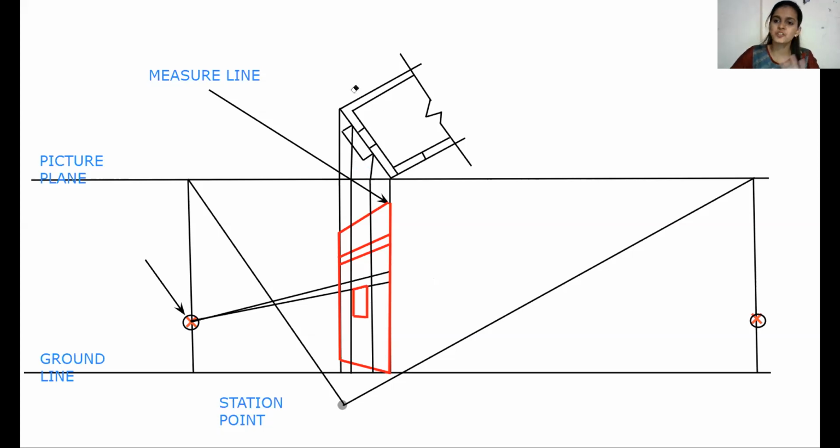I have erased all the projections we used to draw the building and the window. Okay, I'm using only these projections of the backside chhajja points in our plan. So here we can see it's a rectangle. I'm showing it using a yellow color. Okay, so above the window we are going to find four lines. Which 4 lines? The 2 inclined lines for the chhajja projection and two vertical lines from the backside chhajja points.